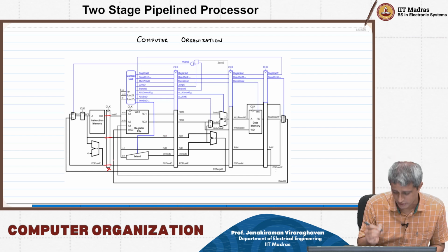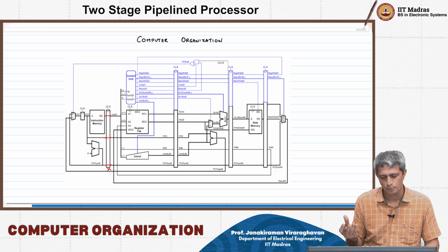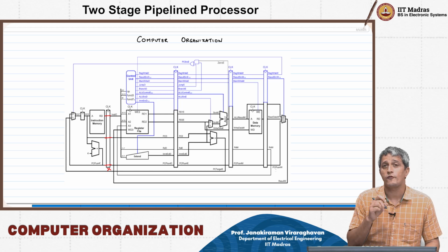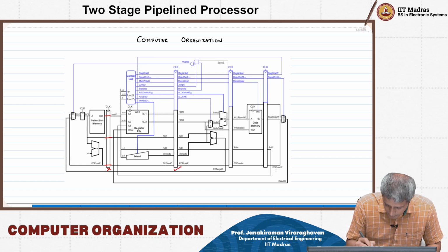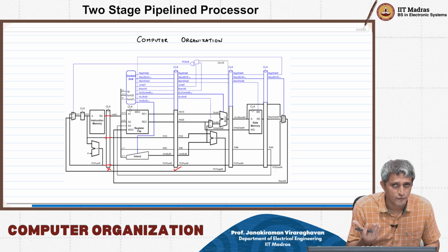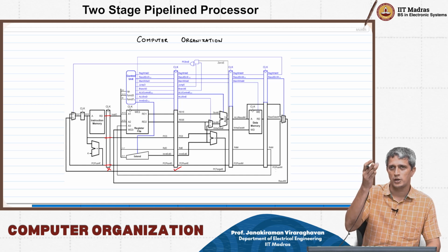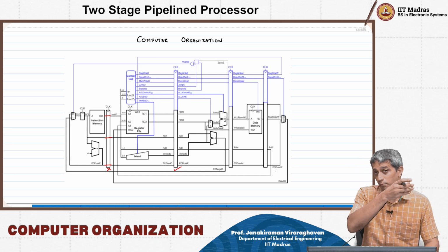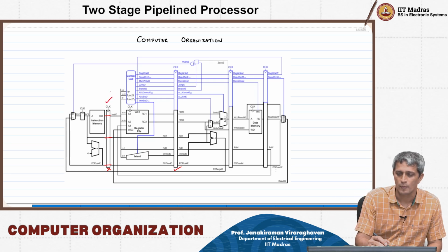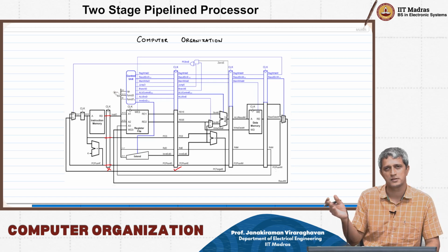Likewise, I'm going to bypass this guy here, right? So the PC plus 4 also can just be called PC plus 4D signal, right? The only flip-flop that I'm actually going to retain is this particular flip-flop that appears right after the register file. Why specifically this? Because it also takes care of registering certain control signals. So if I had kept only this flip-flop, then the control unit is not very different. It's after that, and then that is simply going to remain combinational.